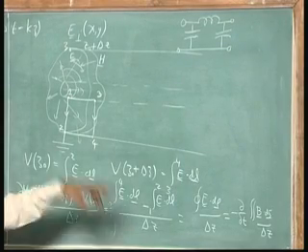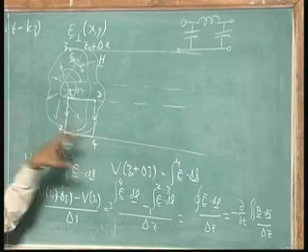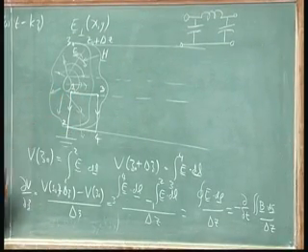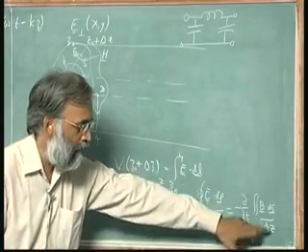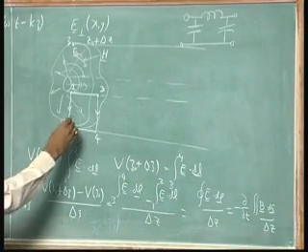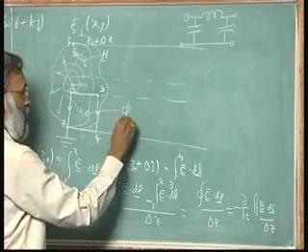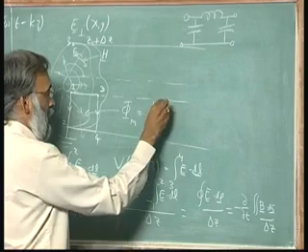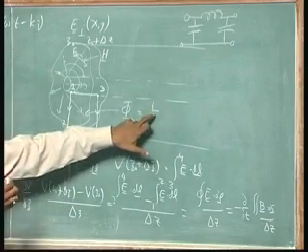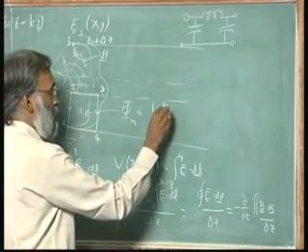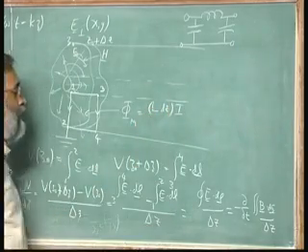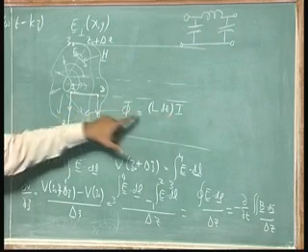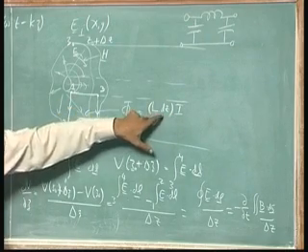Now, this B dot ds is magnetic flux through this rectangle, and the magnetic flux through this rectangle is clearly proportional to delta z. Therefore, this delta z is going to cancel out. How much flux is there? Phi magnetic is equal to L, which is the inductance per meter, times dz times I. Magnetic flux is Li, but in this case the inductance is a distributed inductance.